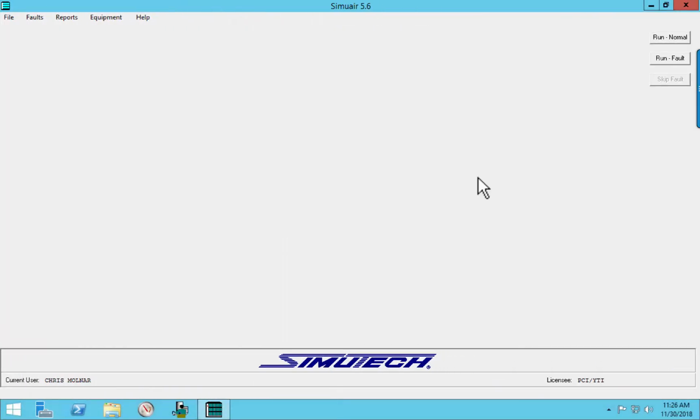Let's talk a little bit about air conditioning troubleshooting. I want to talk about the condenser fan issues first. The reason I want to do this is because I recently asked the students a question. I gave them an example of a troubleshooting where the compressor was running high amperage, condenser fan was running high amperage, and I gave them some pressure scenarios where the high pressure side of a system was running extremely high.